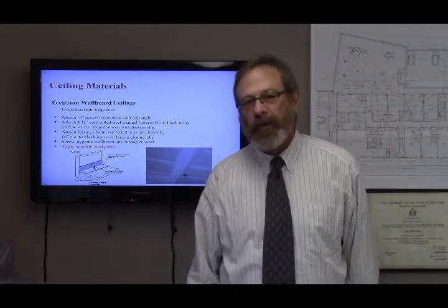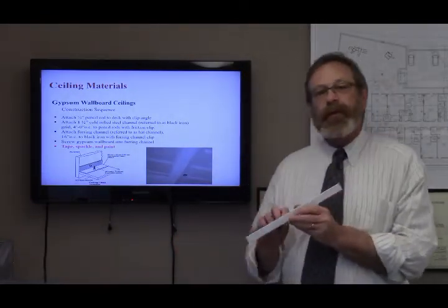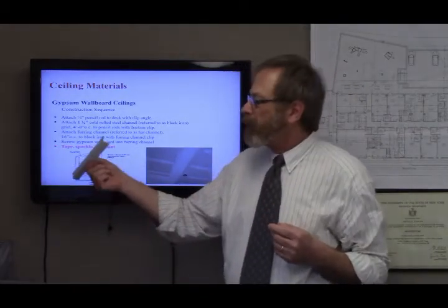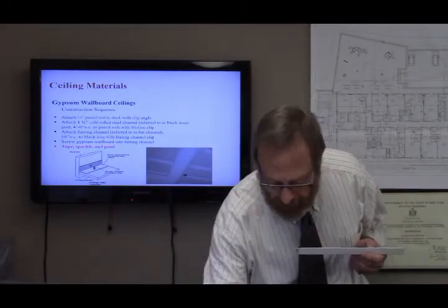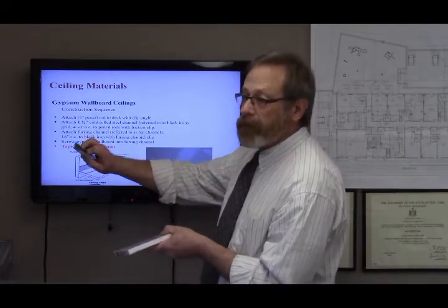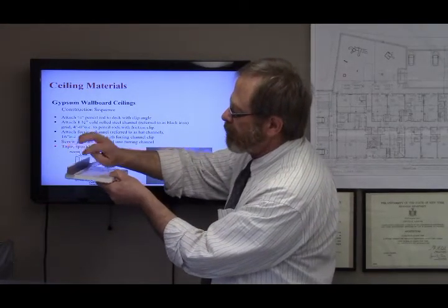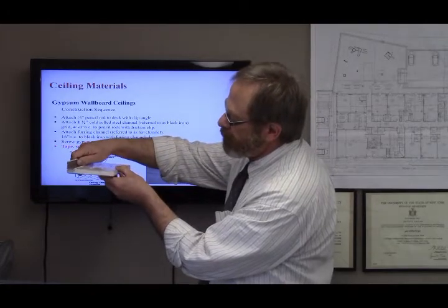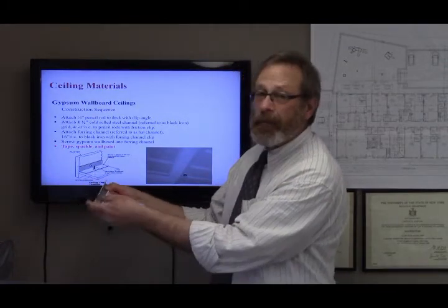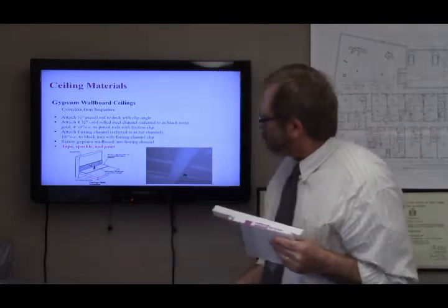At the edges, where the ceiling will meet the actual wall partitions, we hang at the ceiling height a wall angle. It's 1 inch by 1 inch. And for that piece of gypsum board, we will attach a galvanized wall angle to the wall at the height of the ceiling. Screw the wall angle through the wall or partition and screw the gypsum board into that bottom flange of that angle to secure it. Then we tape and spackle the corners.